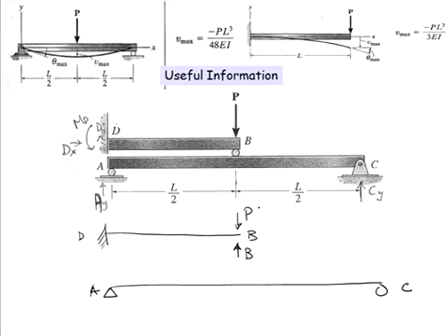So of that load P, some of it will be transferred into the simply supported beam. So if that force there is B, then this reaction here will be P minus B. Yeah? Now if there's a force up here B, there's a force down here B. And because this is symmetrical, that will be B on 2, and that will be B on 2. Yes, Lizzie, but we don't know what B is. You're right.